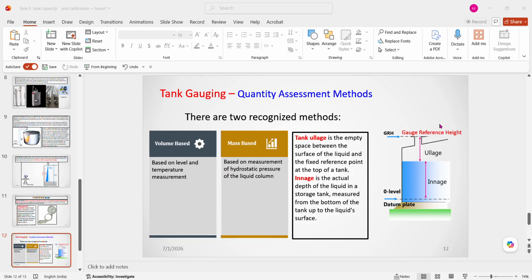This is two-wire IS HART. What is the two-wire IS HART? Now the function is a two-wire loop. The gauge receives DC power, and the AC that is coming is converted to DC power, and it communicates digital and analog data over the exact same pair of wires.